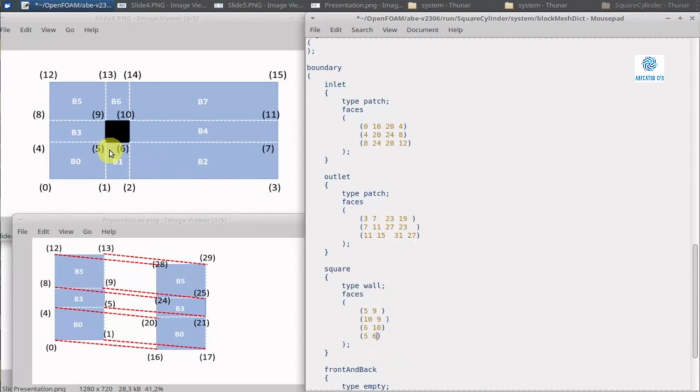This might be a bit confusing. How do you decide the right-hand direction for this face? What you should keep in mind is that inside these blocks, V1, V0, etc., we want cells, so we have a computational domain. When defining the face shared between 5 and 6, my right hand must be oriented so my thumb points out of the face. It must not point inside.